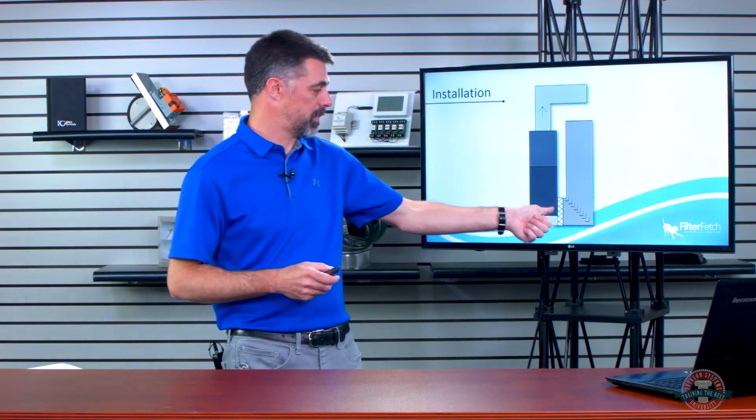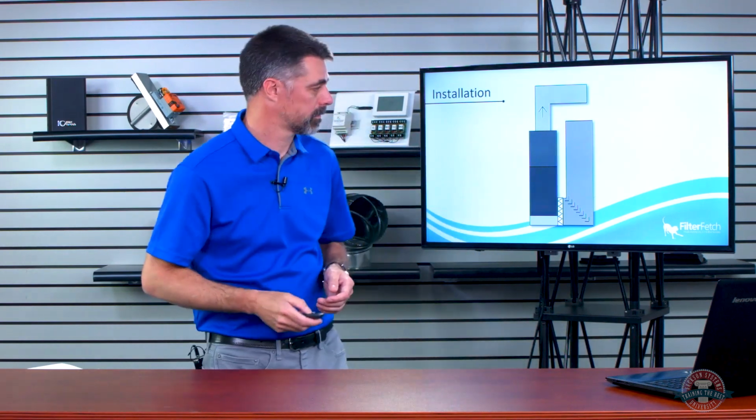So that's an important piece, to be able to get that air across to the opposite side of the blower so that we feed that blower evenly. Because if we're trying to shove all the air into one side of the blower, it's not going to work, and it's not going to evenly distribute the air across the heat exchanger or the coil up top.